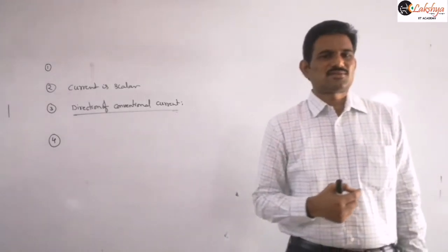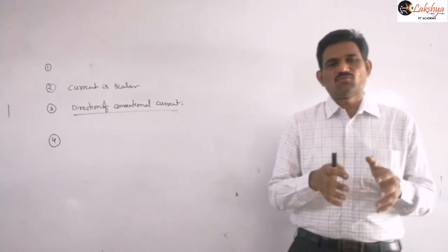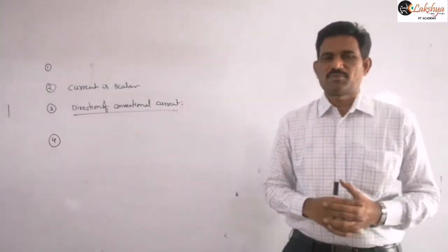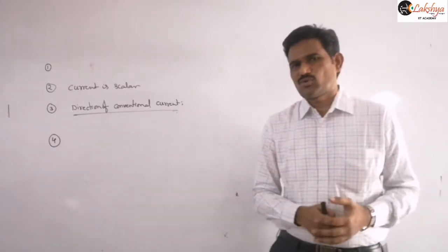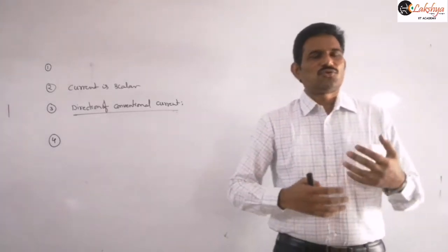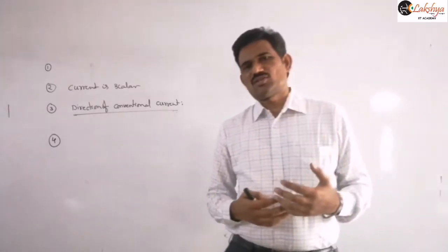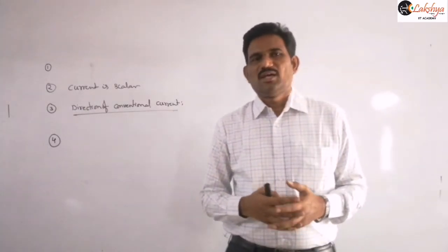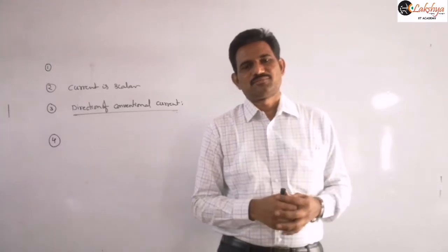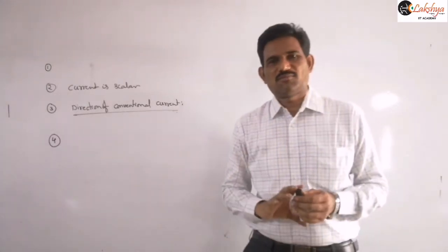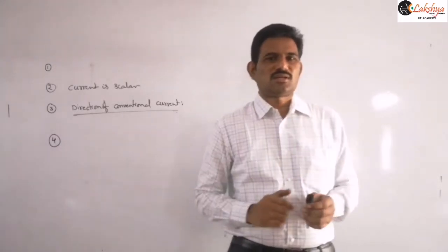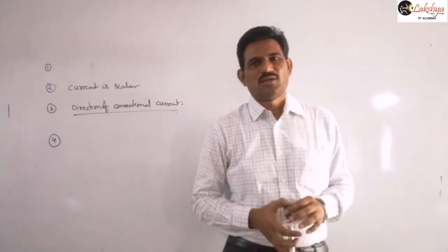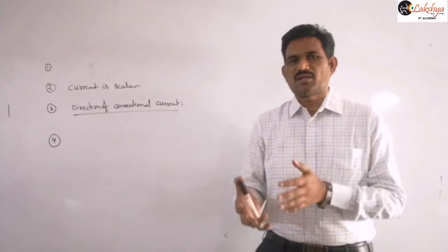In insulators, all the electrons are involved in bonding, so no free electrons are present inside these insulators, and conduction is not possible there. Even so, if you apply a high potential, or raise the temperature of certain materials, the insulator may become a conductor. That is a totally different phenomenon, which we discuss in capacitors: breakdown of the dielectric, called the breakdown of the insulator.